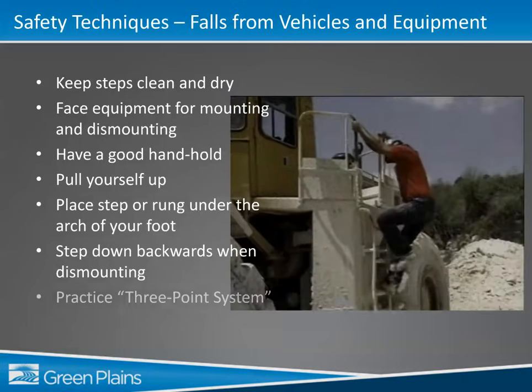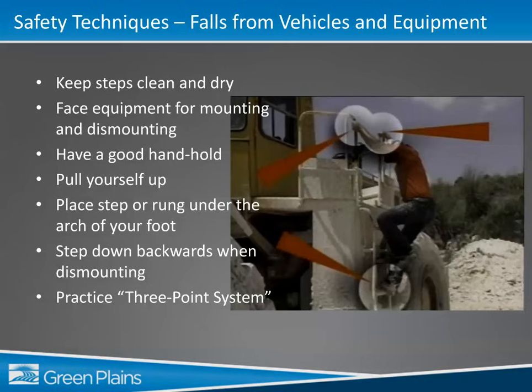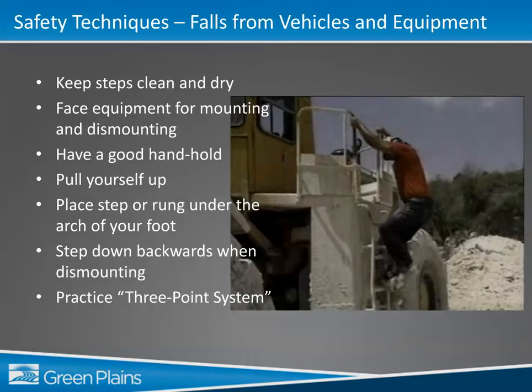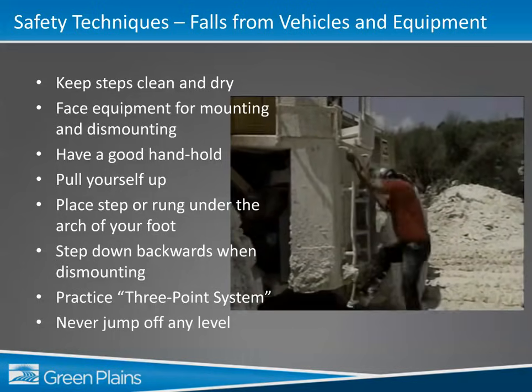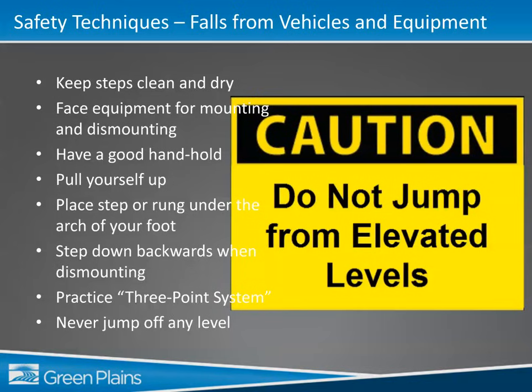Practice the three-point system. This system can significantly reduce the chances of injuring yourself through a slip or fall while entering or exiting a vehicle. The three-point system means that 3 of your 4 limbs are in contact with the vehicle at all times. Only one limb is in motion at any one time.